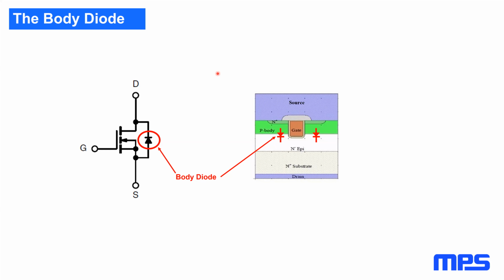Are power MOSFET gates nowadays always protected against ESD? Are there Zener diodes or something else built in that limit gate drain voltages to plus or minus 20 volts or whatever the actual limits of the device are? Good question. They are not all protected. There are some which are, where they actually put a protective Zener there.